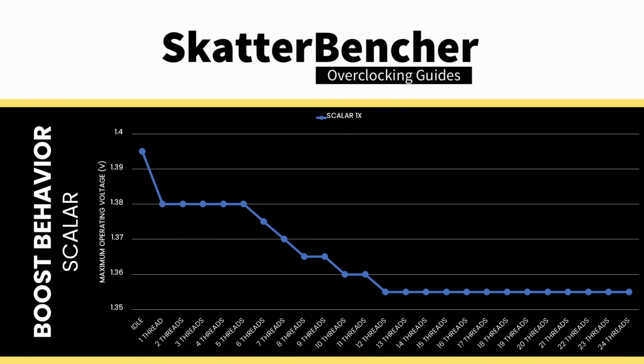For Zen 5 Granite Ridge processors, it seems that scalar is making a comeback in the overclocking strategies because the primary limiter of the operating frequency is the operating voltage. When all cores are active, the maximum voltage is 1.355 volt. The maximum voltage when a single thread is active is 1.38 volt.